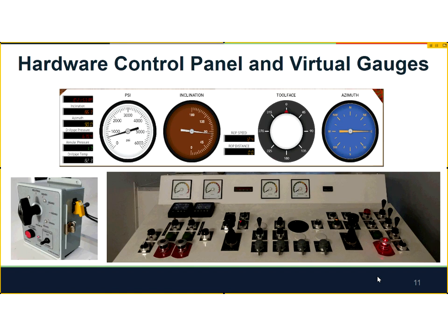In addition, there's an external mud pump control. This term basically controls how many gallons per minute of drilling mud are being forced through the drill string. And then this is a virtual gauge that we developed that tells them the inclination and azimuth and tool face angle, which is essentially the orientation of the drill bit relative to up. And it's in addition to some other things about pressures and temperatures that are being recorded underground.